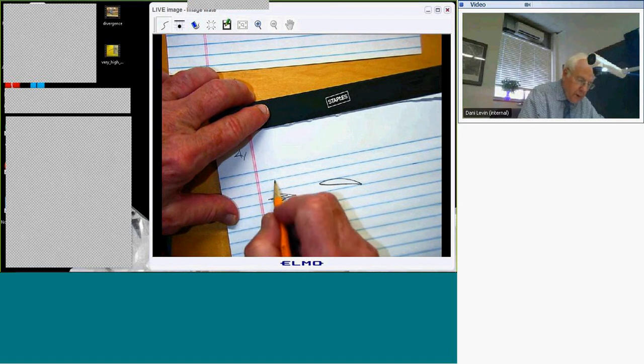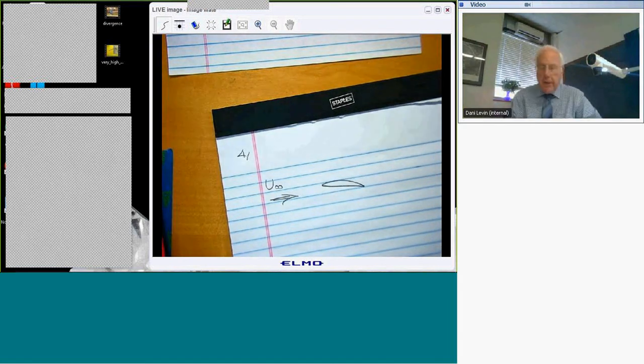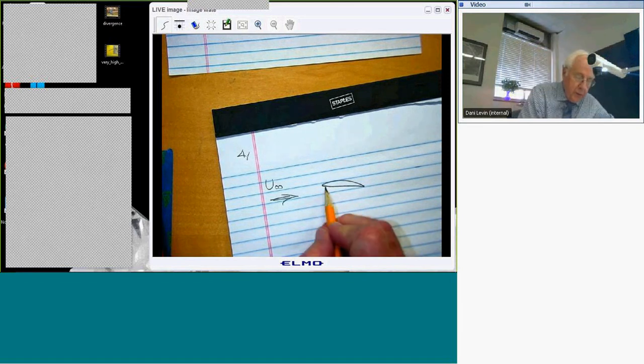And I have the oncoming stream. One of the physical characteristics of transonic flow is, whereas in subsonic and supersonic flow, the actual shape of this airfoil doesn't matter very much in terms of generating lift as far as the thickness is concerned. I mean, what I can do is I can usually replace that airfoil with a mean camber chord, which allows for curvature and allows for possible motion.